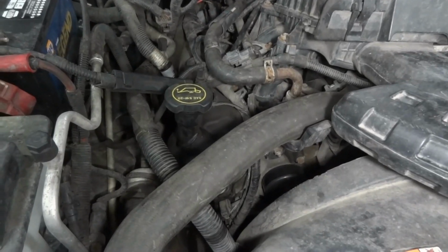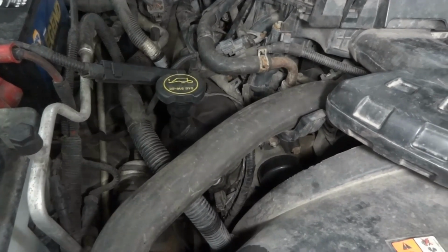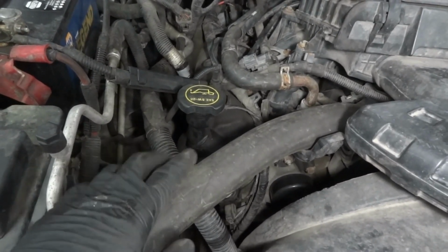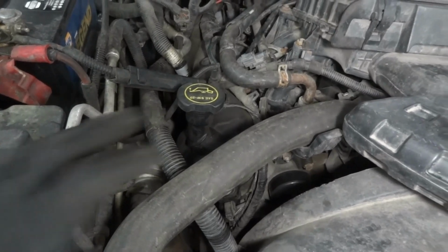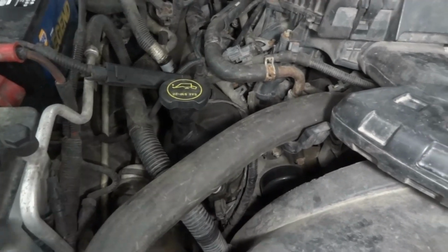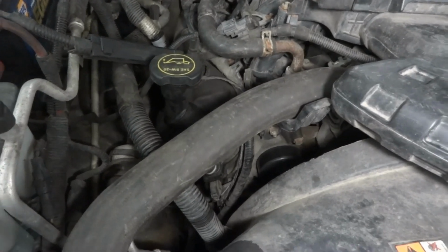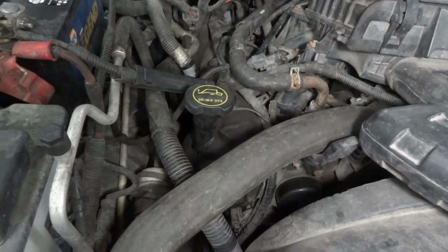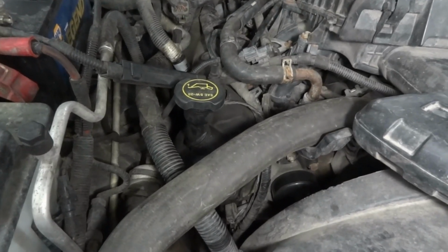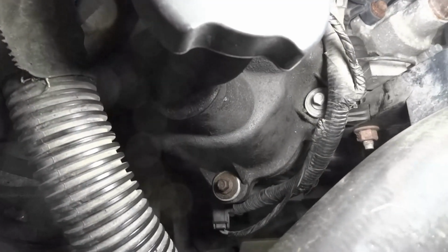Do you think it's hard to install? I told him, well, it could be easy or hard, but you may not need a sensor. It could be a wiring issue, or it could be a lot of things. I've seen these engines, especially these 5.4 engines, have a timing jump and cause cam sensor trouble codes to be set while the problem was the timing. So I was like, there are so many variables. You could just have a bad sensor also, or a wiring issue. When I told him that, he said, you know what, I'll bring it to you so you can look at it. If it needs a sensor, then I already have the sensor. I'm buying the sensor from AutoZone. I said, okay, fine. Well, I'm glad, because in this particular case, he doesn't need a sensor.